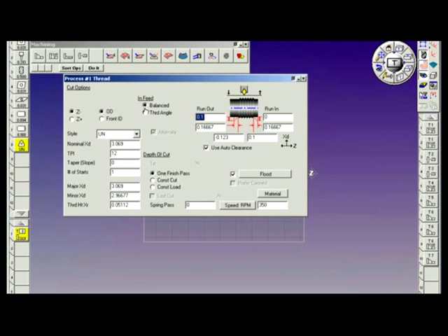There's balanced and thread angle. The difference being that with balanced, the insert enters the work at 90 degrees or perpendicular to the cut. Thread angle enters at 29.5 degrees, which is like using a compound slide on a conventional lathe. If any of you guys have ever done any single point threading on a conventional lathe, you know that the compound slide is set at 29.5 degrees, and that's how you approach the work.